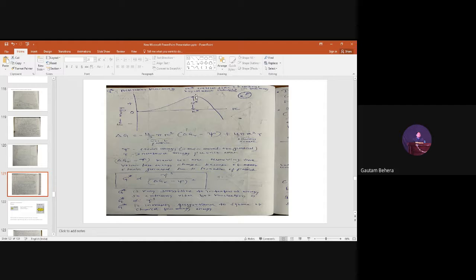So that's why you can see the graph going downward towards the negative part, and this is the positive part, right? Initially when r is smaller, suppose the size is this much, what will happen to the precipitate? It is not stable, so it will dissolve again into the matrix.